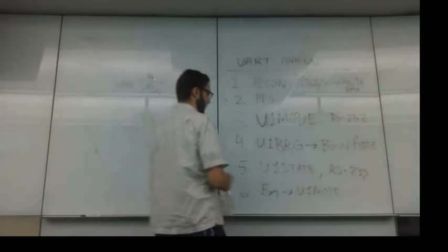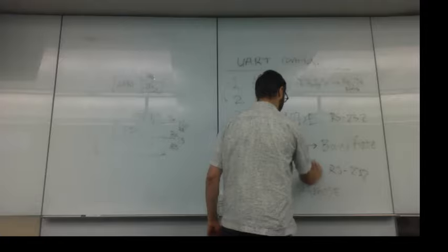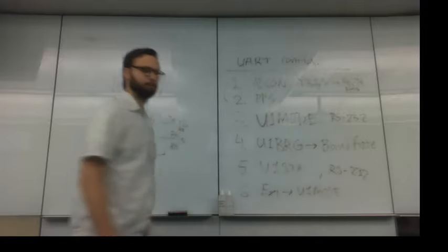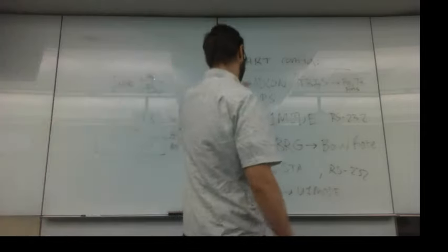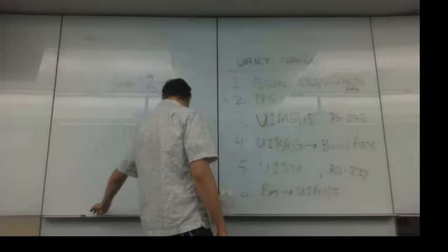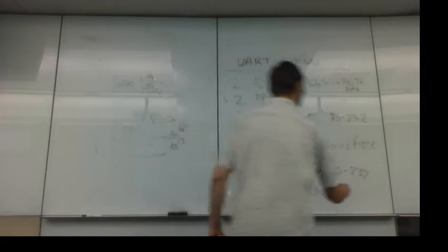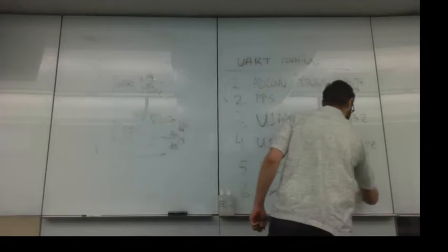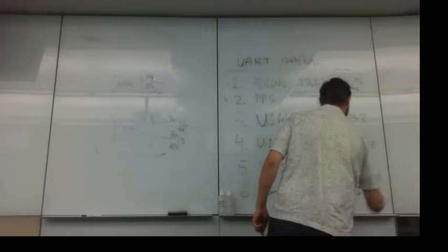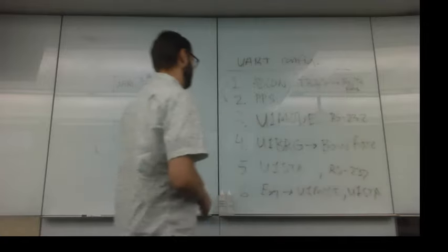Okay, so it's called U1STA. And so you don't want to enable transmission until you've set up all this other stuff. So you enable U1MODE and U1STA. So that's your final step.